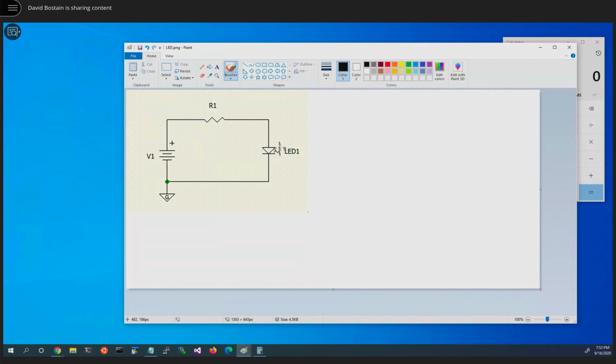What are the assumptions we make about an LED? What is the drop across it? Well, first of all, we need to check to make sure it's in the circuit in the correct direction. Is it the correct direction? And the answer is yes. The plus end is hooked to the plus end of the battery. The negative end is hooked to the negative end of the battery. What voltage drop are we going to have across the LED? So we would give it a name of VF, or VLED1F. I just put VF because we know it's the forward voltage. What would that be? Put it in chat.